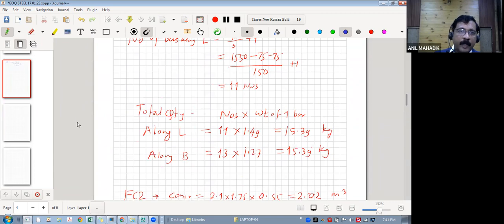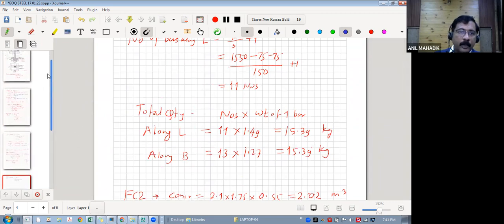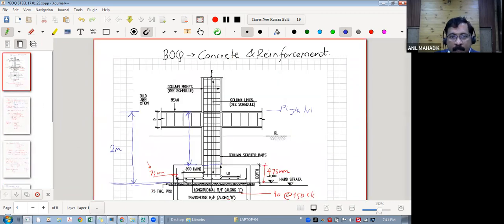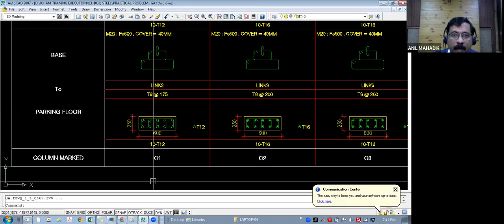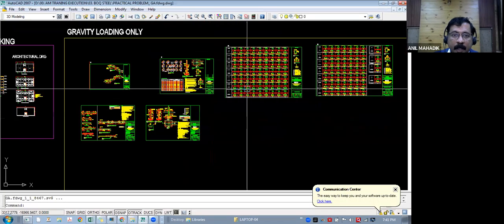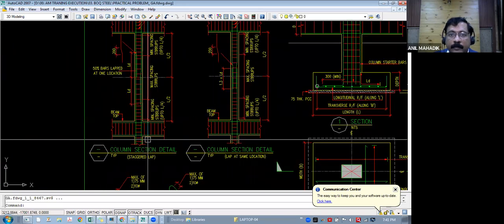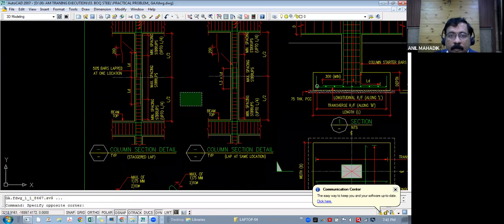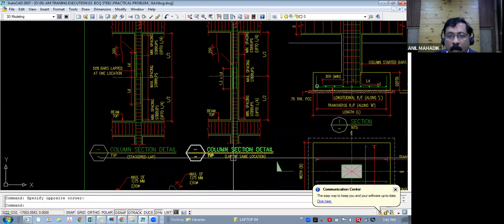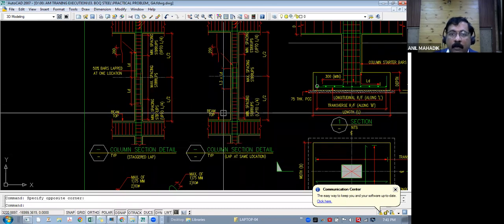Now for the reinforcement, there is a question to you. You have understood that there is an L of 300 mm. Now what height should I take? Because these bars go till the above floors. But where is that level? So again, check the reinforcement details in the standard drawing. You can see here. If you look at this drawing, let's say there is a footing here, or I'll do one thing.